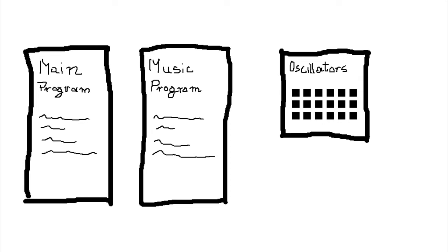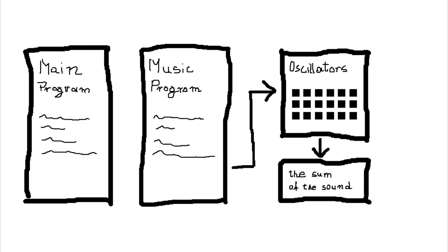With 15,625 Hz sampling and a 16 MHz processor speed, one oscillator uses an average of 2% of the processing power of the processor. Each oscillator can change the waveform frequency, volume, and phase if, for example, the wave needs to start all over again. The library automatically calculates all the oscillators and adds them together. This sum of waves is then converted into the corresponding PWM signals in the further part of the library. The settings and types of sound output will be discussed in the library configuration section.